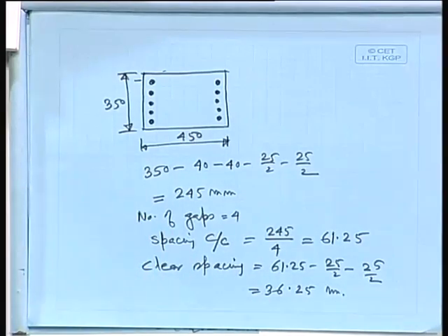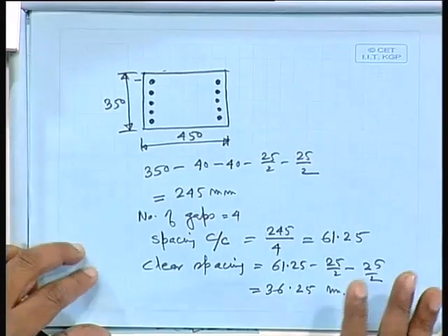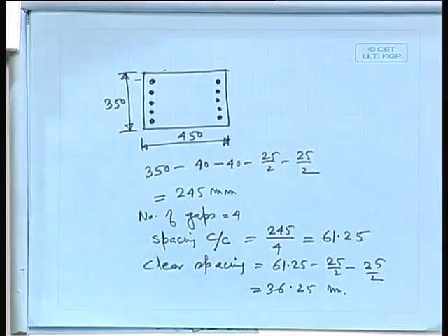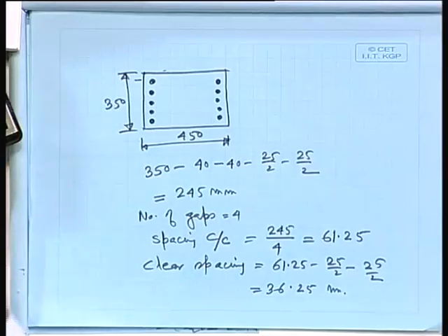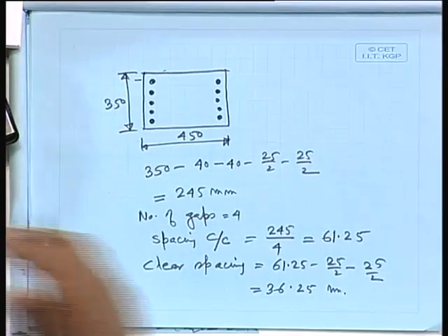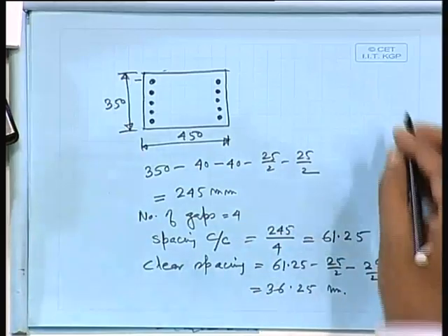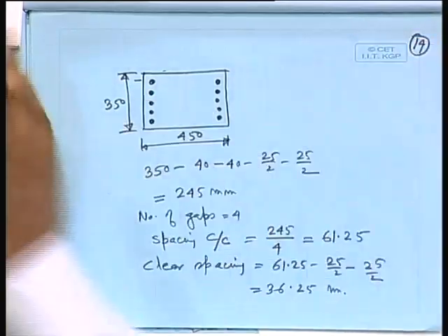So we have enough gap, because we have to provide that for the coarse aggregate. So that is why it is very, very important in your reinforced concrete design that your clear spacing, all those things, that is detailing, that we have to specify. Okay. So let us conclude at least this particular class today. We shall continue in the next class. Okay. So thank you.